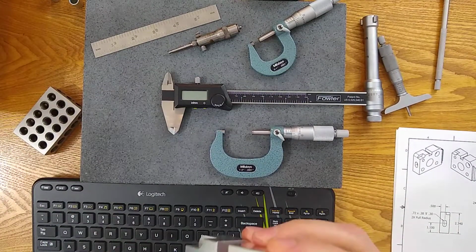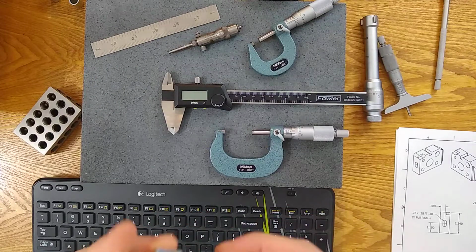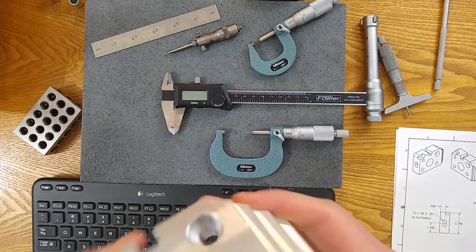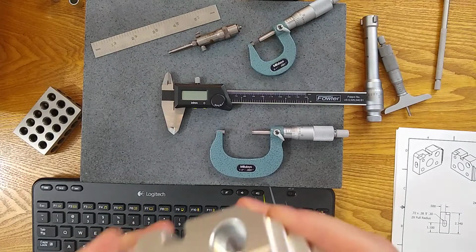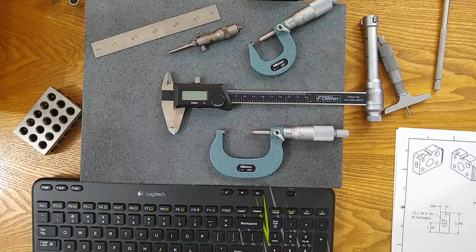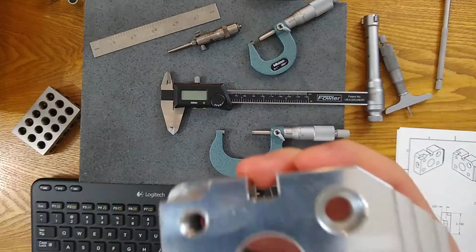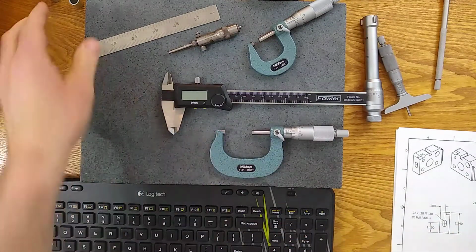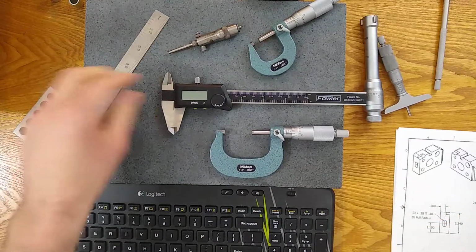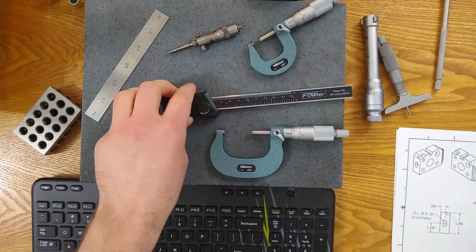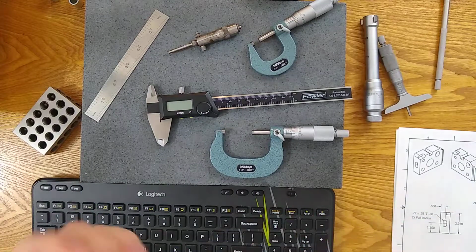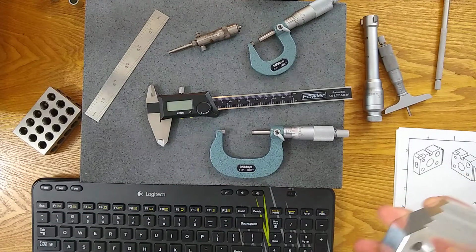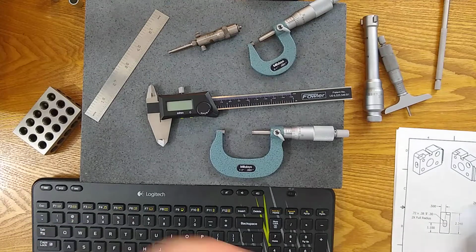So, for holes, we had a whole subject just on hole inspection where I gave you like 6 or 8 different tools you can use to inspect a hole. Here: calipers, pin gauges, bore mics, telescope gauges, dial bore gauges. For outside lengths, across a feature, you can use calipers, micrometers, steel rule, height gauges, CMM. I have some of these here. And then inside distances, again, we have calipers, gauge blocks, pins, height gauge, CMM. Not to mention angles, threads, and profiles.